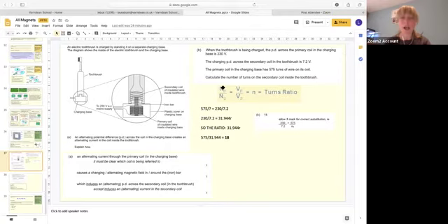So I've got NP equals 575, because that is the primary coil with 575 turns. I need to find out what value I'm going to put up here. This is what they're asking me to find out. But I know that the answer of this sum is equal to the answer of this sum, essentially. So there's a ratio involved. If I have 230 here with my volts, and 7.2 here, because that's the other value given to me, and I divide these, the factor is 31.944. So that is the value I'm going to be using here.